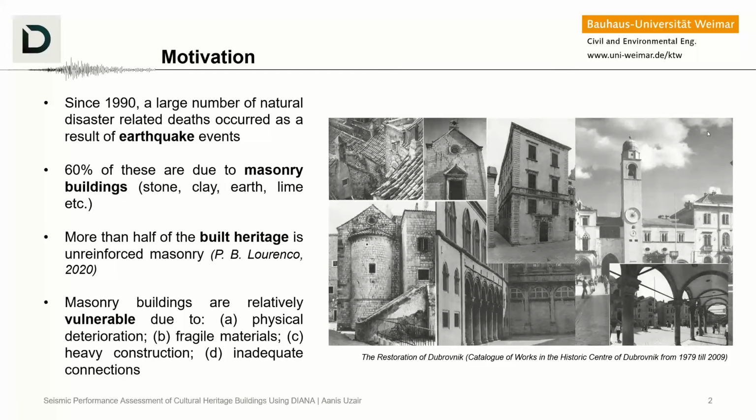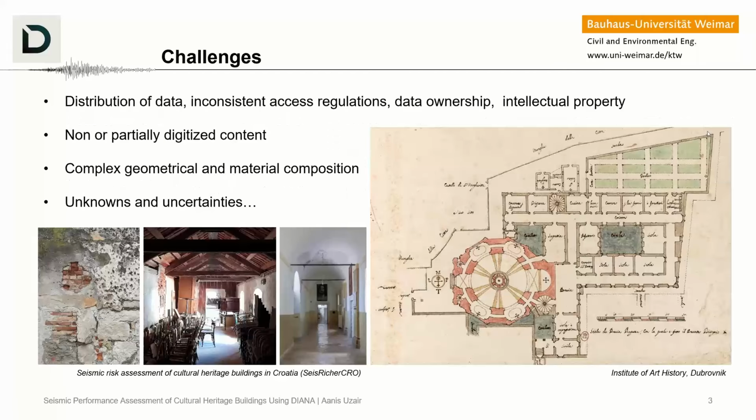And the buildings, because they have stood for a very long time, they suffer from environmental degradation, have a very heavy weight, and irregular geometrical openings, which cause stress redistribution to areas where you don't want these stresses to go to. A part of the problem also is in the inadequate connections of the walls to the floors, so from the wall-to-wall connections. And all of this combined together makes these buildings extremely vulnerable, particularly in the case of seismic action or lateral motion.